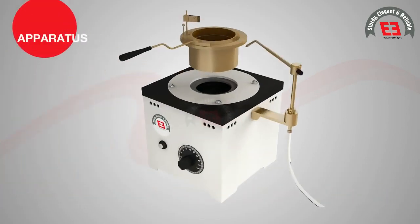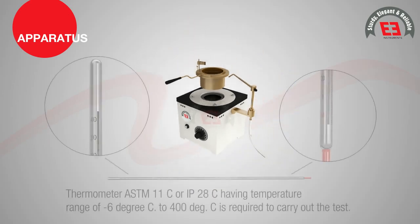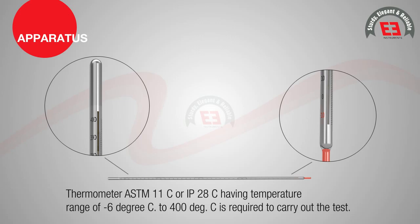Apparatus. The apparatus consists of a test cup, heating plate with temperature regulator and test flame applicator. Thermometer ASTM 11C or IP28C having temperature range of -6 degrees Celsius to 400 degrees Celsius is required to carry out the test.